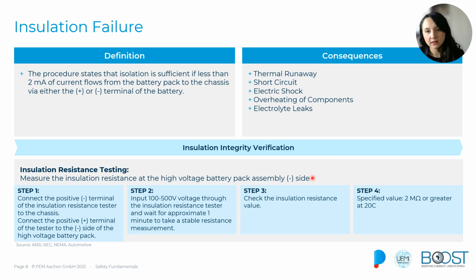But on top of that, we have the insulation integrity verification. That is something that happens during the assembly process of the battery, but it also applies in general when we are operating or when we want to operate with these systems. Basically, this test measures the insulation resistance of the high voltage battery pack, and by measuring that resistance, we can define if there is good or bad insulation in our system.